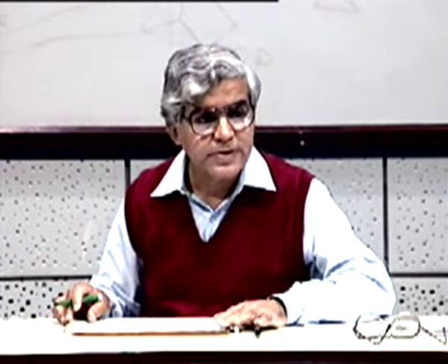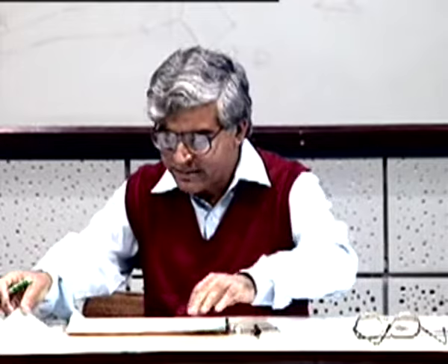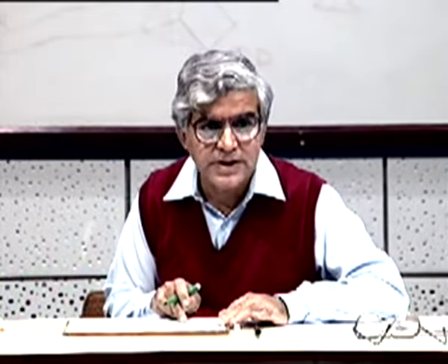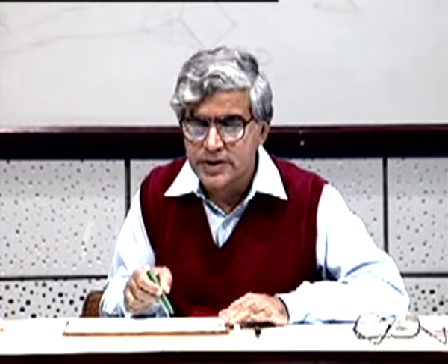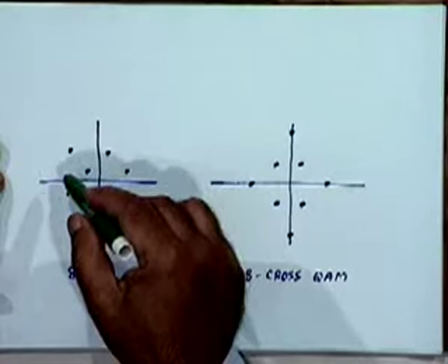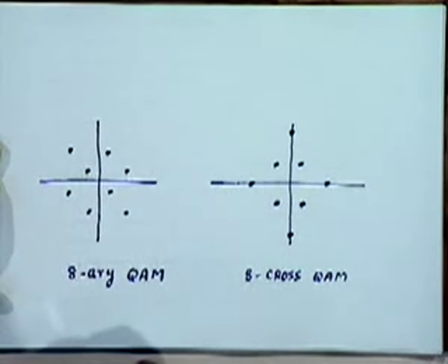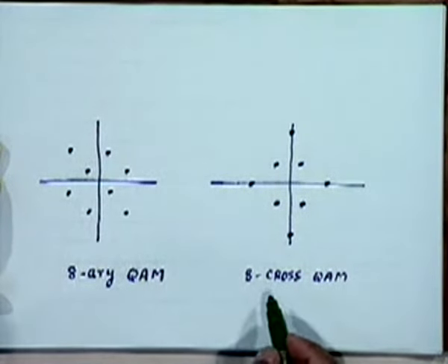These are other examples just to show that we have an infinite choice here in designing a constellation, right? There are a lot of variations possible. I can have an 8-level QAM in quite a different way. This is yet another way of designing a QAM system in which I have both amplitude and phase variations possible, some kind of a regular grid, not necessarily the square grid that I had to start with, right?